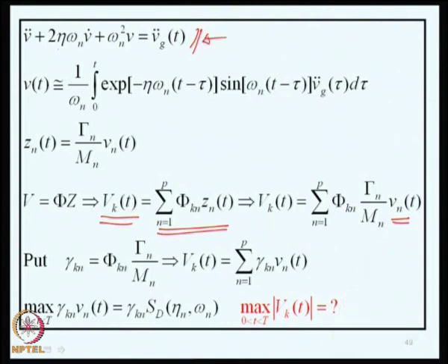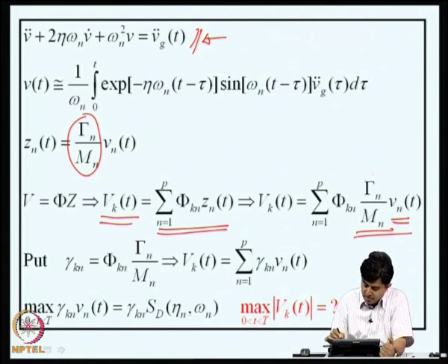So, this is actually the quantity that is used in response spectrum, and that is what I will multiply now, because the excitation is multiplied by this factor. I need to find the time history of the generalized coordinates. I need to simply multiply this Vn of t by this participation factor. Now, I put gamma kn, I will introduce all this, and I will introduce a single number, I call it gamma kn, and in terms of Vn of t, the response is given as here.